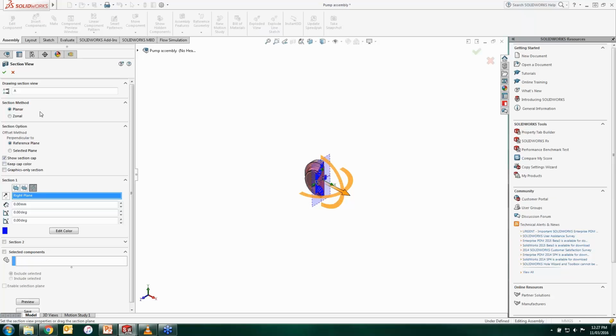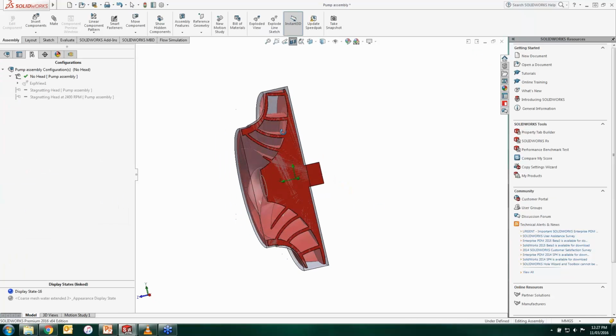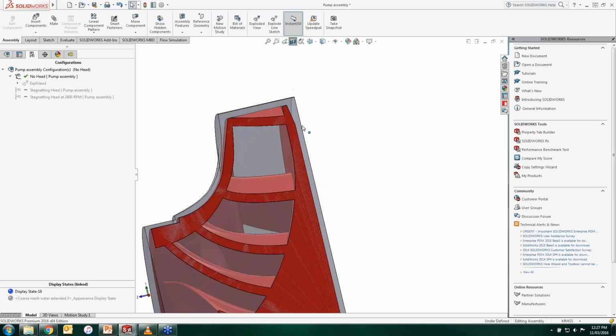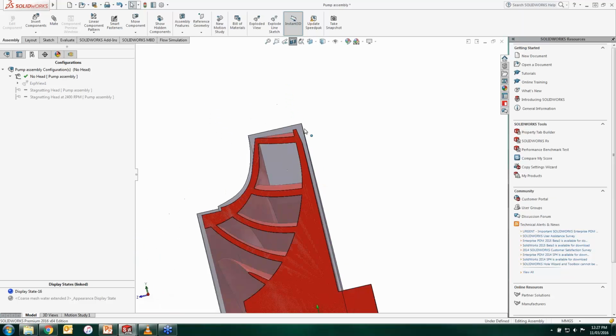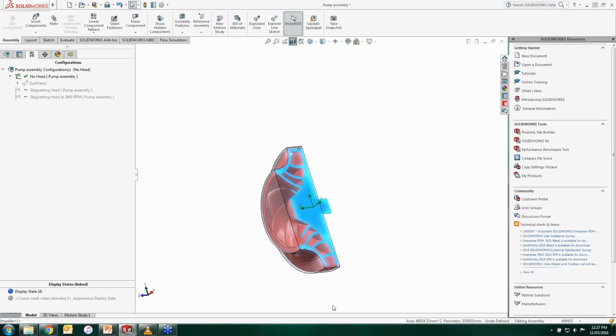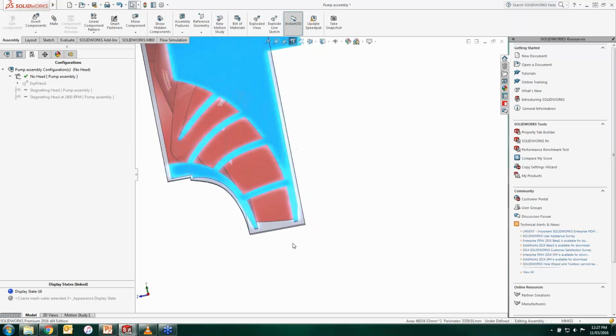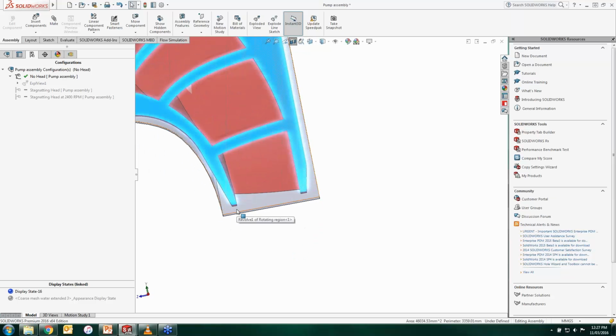Now look guys what I've done. Here it is, and you can see basically what is being created. The impeller is here as the red component, and you can see the dummy region is going around it with some gap. Not a very huge gap. We're talking about something considerable.